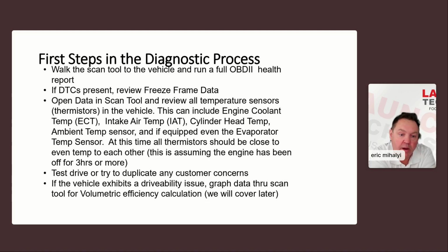I'm going to try and take it out on the road where I can get it up to that speed, recreate the problem, recreate the load, and see if whatever happened for the customer that caused that, I can duplicate it, right? Nowadays, we're told what happened at the time that this failure happened, what the car was doing. So we have no excuse for guessing and going, I just can't duplicate it. No problem found, and shipping it down the road, or telling the customer when it happens again, bring it back. We have the ability to hopefully try and recreate the problem based on what their driving conditions were.